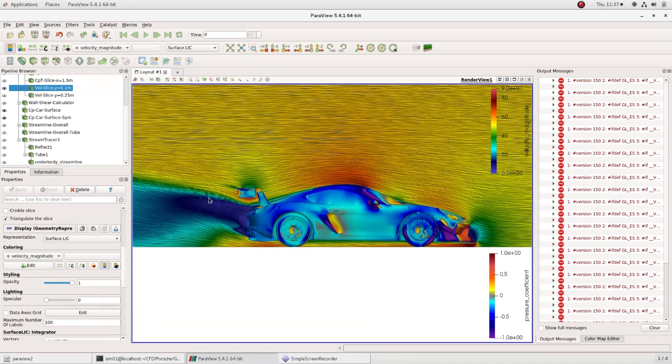The dead water region, the blue separated area on the rear, can easily be seen. You can see the recirculation right around the license plate. The dead water region is pretty small because of how our diffuser improves flow behind the rear of the car. The different slice location just shows the same data but in a different location on the car. This one is 250 millimeters from the center line, while the first one was 100 millimeters from the center line.